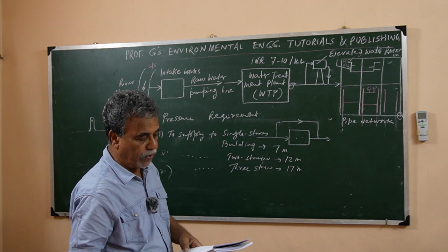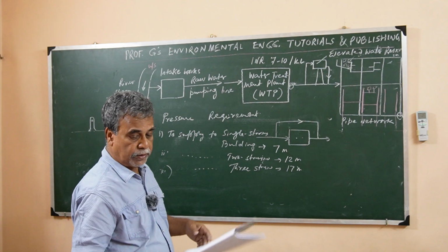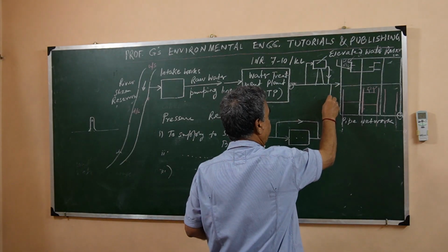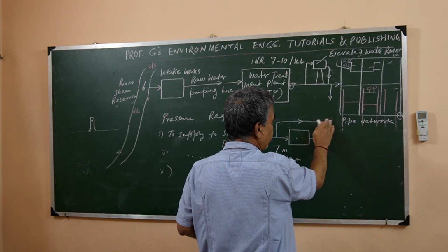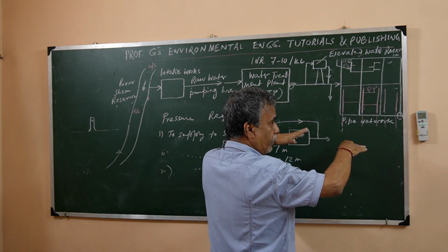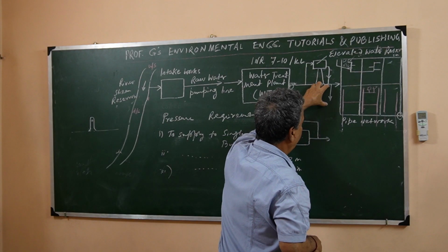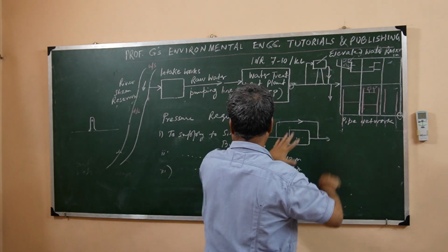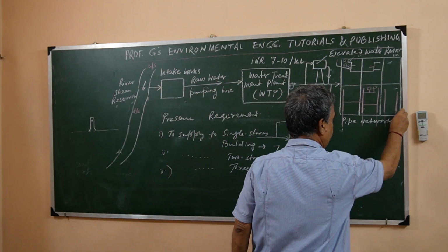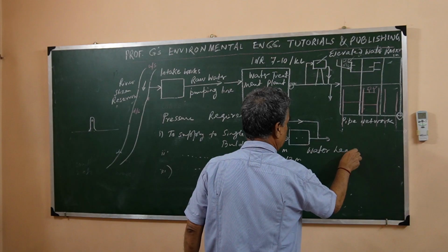And for meeting the firefighting demand, this is boosted by fire engines also. That means in the water supply system, this is tapped from the main line, and the pressure is boosted according to the requirements to extinguish the fire. So what I am trying to say is that this 7 meter of head, these are all in terms of water head, equivalent to water head.